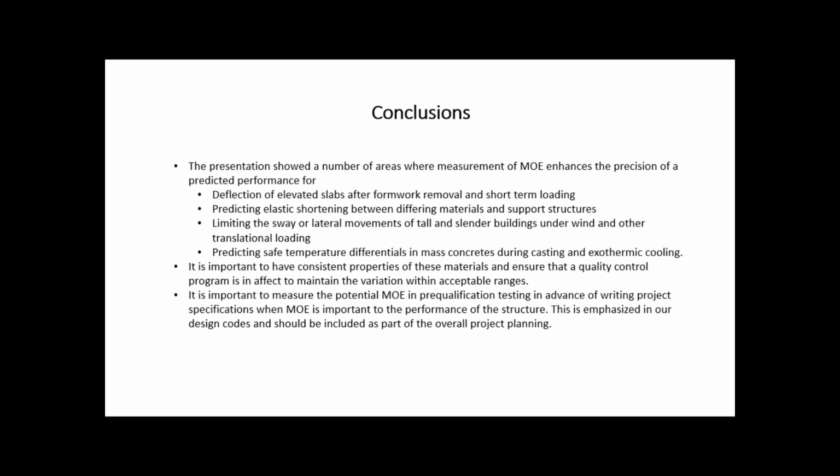It's important to have consistent properties of these materials and ensure their quality control program is in effect to maintain the variation within acceptable ranges. It is important to measure the potential MOE in pre-qualification testing in advance of writing project specifications when MOE is important to the performance of the structure. This is emphasized in our design codes and should be included as a part of the overall construction plan.